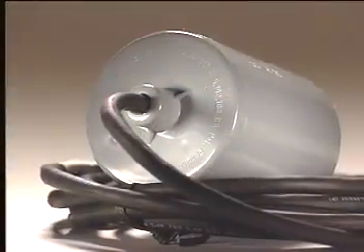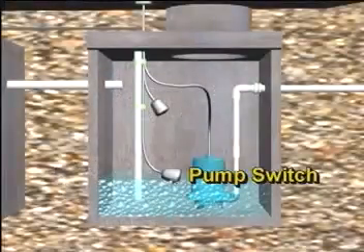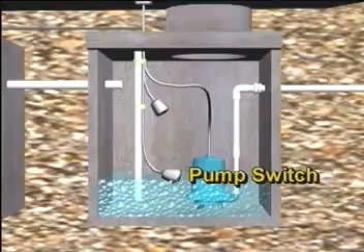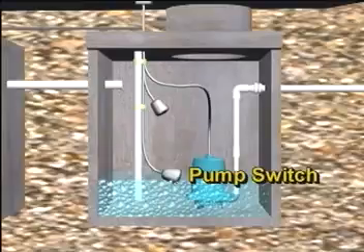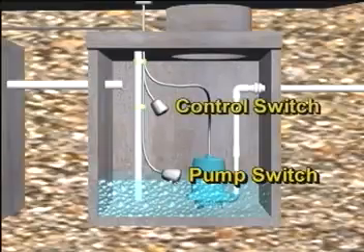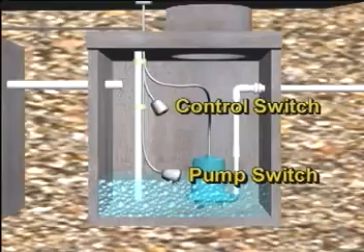Switches used to regulate these pumping functions are usually classified in one of two categories. Pump switches, capable of handling the higher amperage associated with direct control of a pump, are considered wide-angle, operating through an arc of 85 to 90 degrees, which allows the switch to control the level of effluent between upper and lower limits. Control switches are normally used for pilot duty with control panels and alarms. The amperage is usually limited to 5 amps and the operating angle is narrow, usually 3 to 30 degrees.